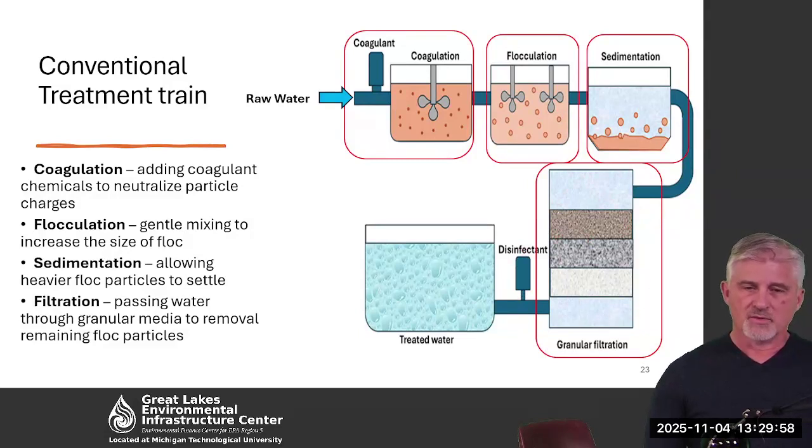So we put that through some media, which could be all sorts of different types. We could have several different types. The idea is that the spaces between the particles are small enough that it pulls the floc out. Anything that escapes through sedimentation gets removed through filtration.